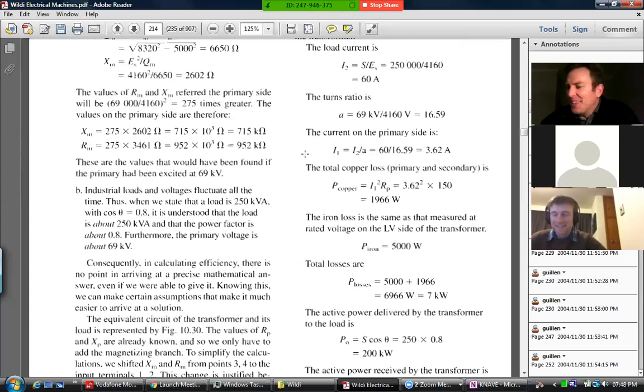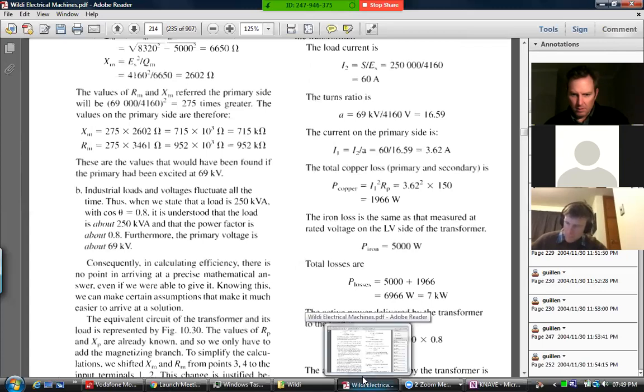I just had a question on the shunt generators. You know how you do the volt drop on the series resistor? Yep. When you go to do the motor version, and no, the long shunt, and the series resistor is on the other side, between the armature and the shunt resistor, when you're working out the voltage or the EMF you'll be generating, do you have to take into account that voltage drop across the series resistor?